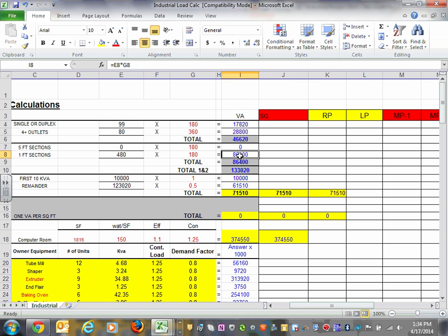It's really easy. You take the 480 feet, multiply by 180, and that's what you get. Any comments, guys? So we allocated the quads, the duplex, and the multi-outlet assembly based on simultaneous or non-simultaneous. You guys do that all the time. Any comments about that one?